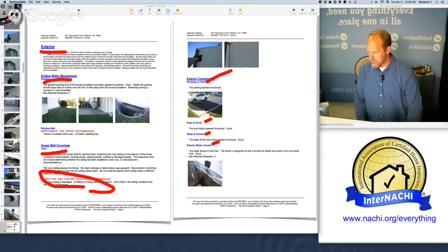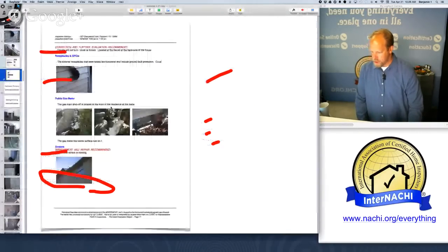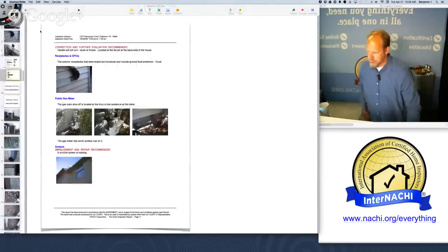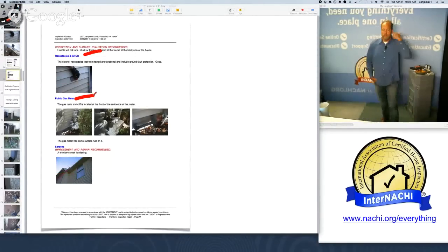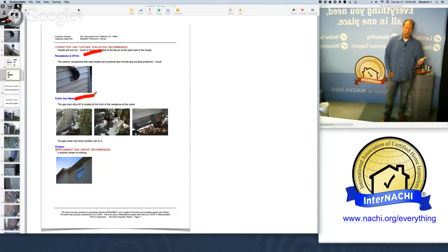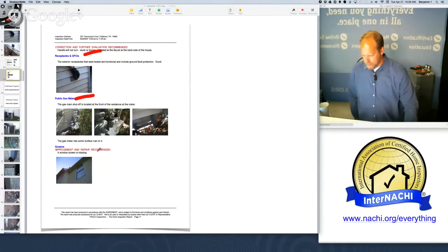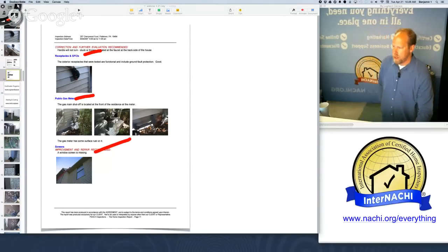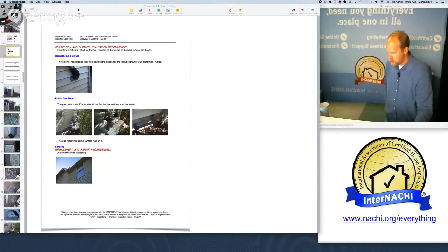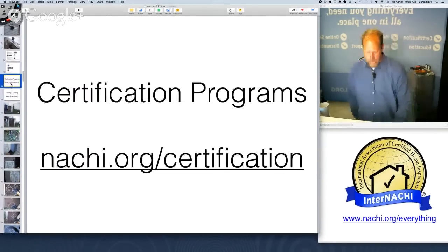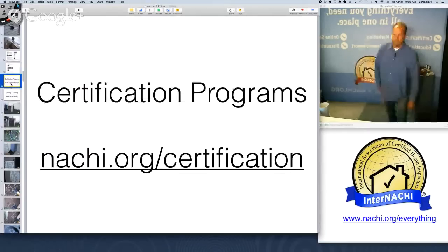Let's go to the next set of pages, the last page of the exterior. We have GFCI, public water, gas meter. So there's gas supplied to the house. That triggers me. I know maybe I have a water source that's gas fired, a heating system that's gas fired. And some of the screens are missing in the windows. So I wanted to tell my client of that, have the seller install the screens.